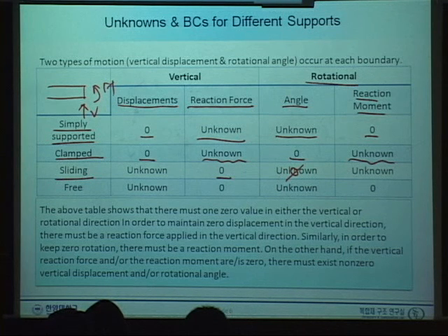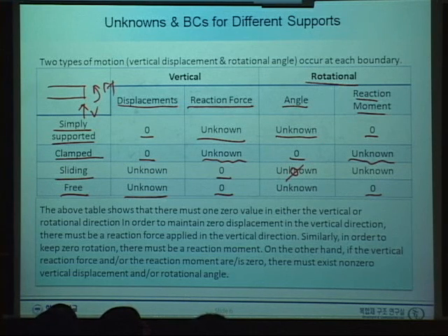And sliding, we do not have any angles, and the moment should be unknown. And how about the free boundary condition? There is no support. Then always there is 0 reaction force and 0 reaction moment. And the displacement and rotation are always unknown.